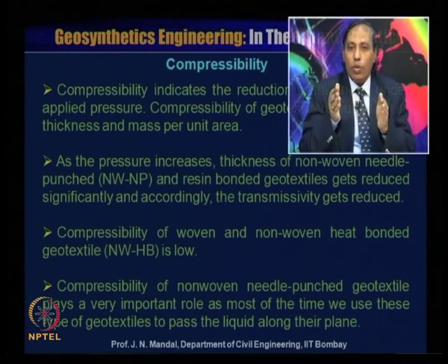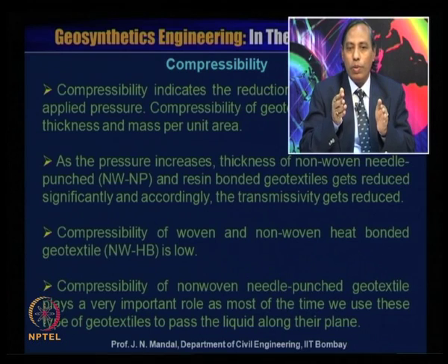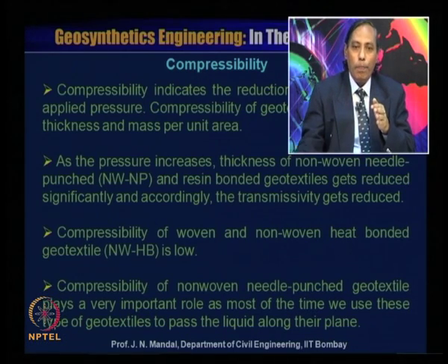Compressibility of woven and non-woven heat bonded (NWHB) geotextile is low. Compressibility of non-woven needle punched geotextile plays a very important role, as most of the time we use this type of geotextile to pass liquid along the plane.